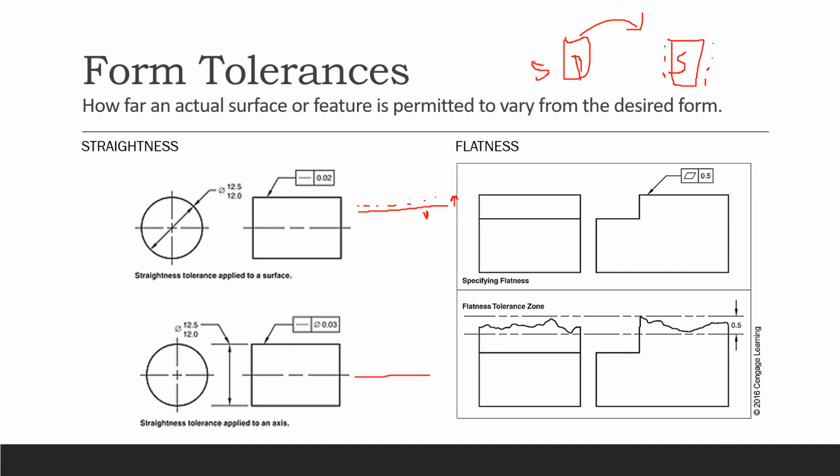The center core can go 0.03. It's a very tiny little thing. Even if it goes up this much, you can't see the difference with the naked eye. You have to use a special instrument to detect that. So this side and that side, you can come down a little bit, but can't go beyond 0.03. So that's my true axis right there. Your axis can be around here and around here. It wouldn't give you any kind of difference because you're within the tolerance zone right there.